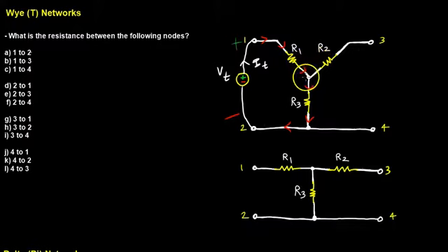So whatever voltage exists at this node is going to be read at terminal 3. If we use a high impedance or high resistance load or measurement device, which usually has a high resistance, it doesn't draw much current and interfere with the measurement. So given that, we can see that there are 2 resistors in series, and therefore for part A, R equivalent is going to be R1 plus R2. Very simple. Let me decrease the size here. Alright, so that's R1 plus R2.